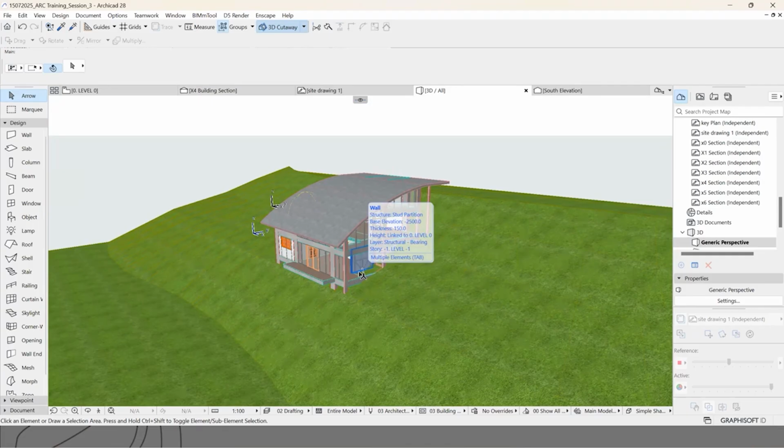Layers in Archicad are actually containers, because some of the other software does a different job altogether. Like using layers, you can assign a line weight. But here we already see that that is done through pens. Layers here are purely containers for assigning certain elements.